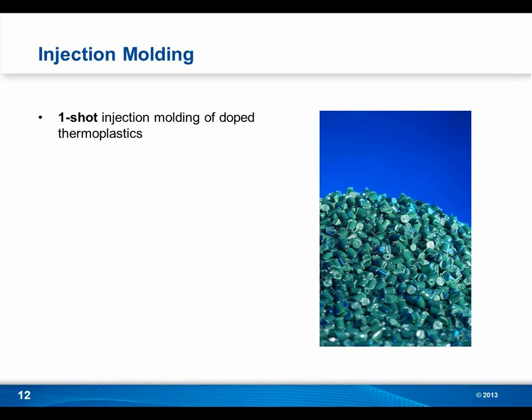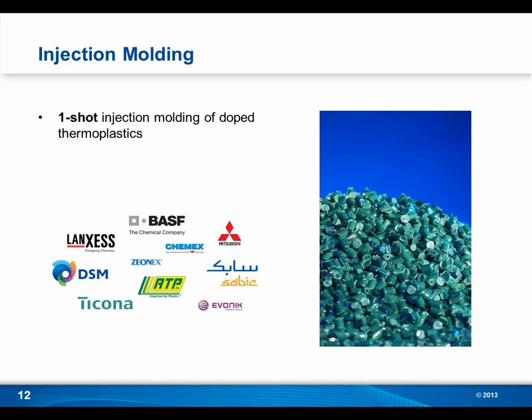So one mold, basically the shape of the part. The plastic is doped, but in its raw form is non-conductive. It's only conductive when you apply the laser power to it and define the pattern that you want to plate. The plastic itself is available from all major suppliers. The people you're buying your plastic from now all carry an LDS grade of plastic, in basically all the various formulations of plastic that are available.